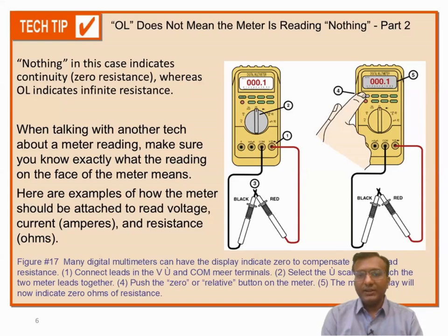And third, we have to touch the probes with each other. Using this method, you can test whether the multimeter is operating in a proper way or not. If there is continuity, the multimeter will give us a beep indicating a continuous circuit.